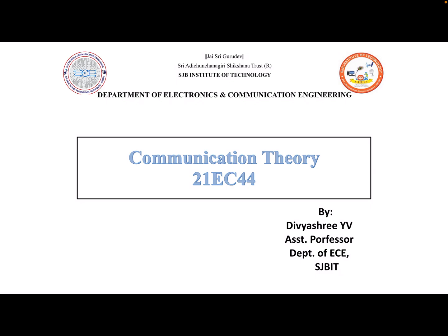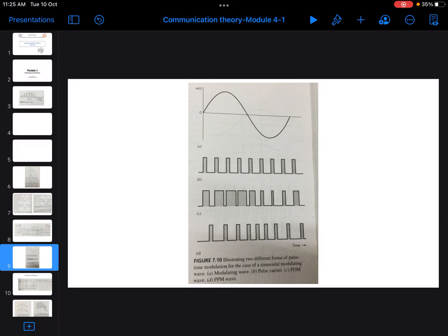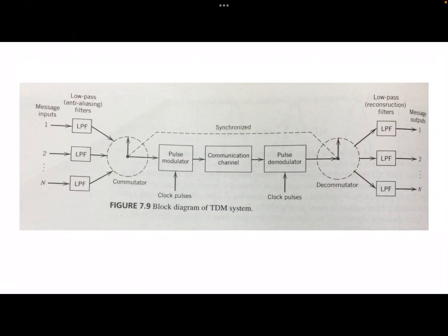In today's video, I will be explaining about the TDM. TDM stands for time division multiplexing. The sampling theorem provides the basis for transmitting the information contained in a band limited message signal m(t) as a sequence of samples m(nTs) taken uniformly at a rate that is usually slightly higher than the Nyquist rate.